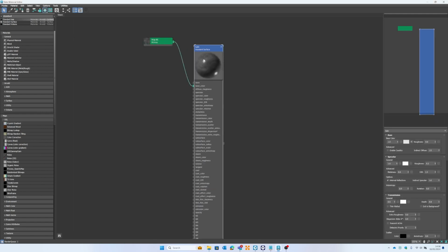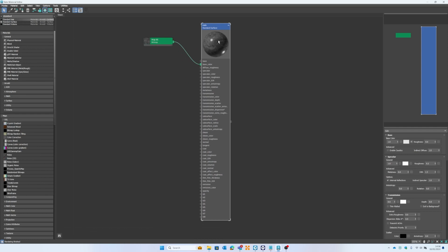And if I just double click this globe here, you'll see that that has updated to give me a kind of image preview of what this thing will look like. If this had some transparency on, we can toggle on the background in that preview to show that transparency. It's also useful to toggle that on because it gives you an appreciation of color bleed and things like that when you're looking at reflection and refraction. But here we've got our color. I want whatever I build in this material to show up in my viewport. So I also want to make sure that this button here is on with the blue background, show shaded material in viewport.